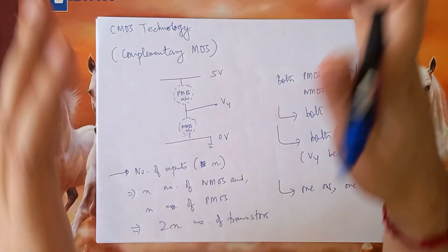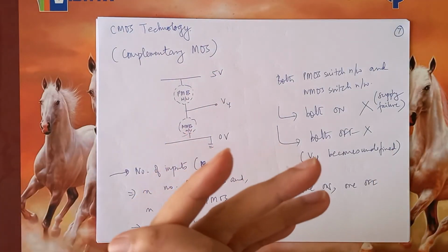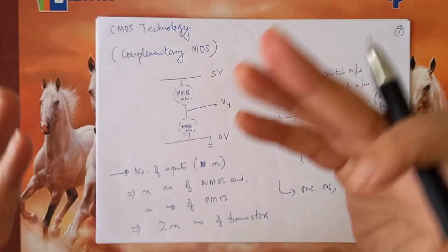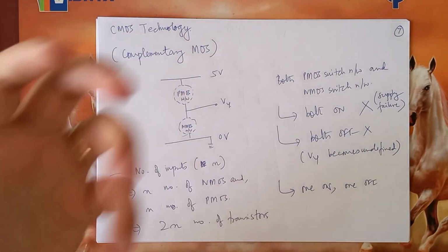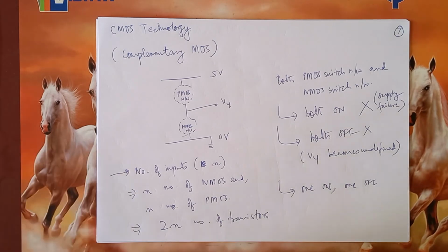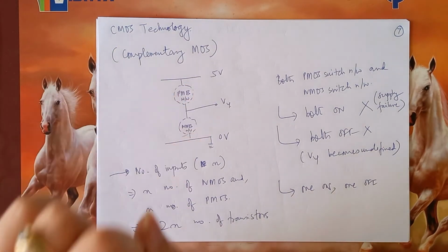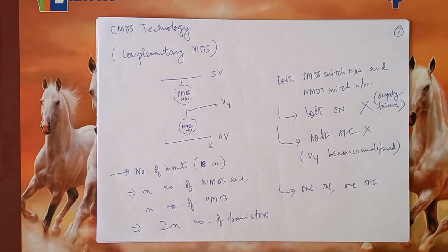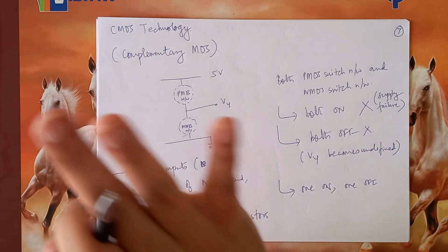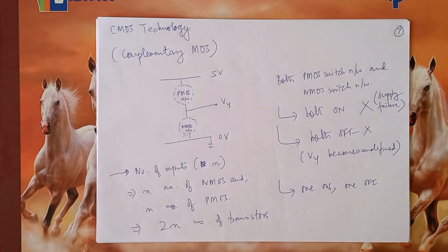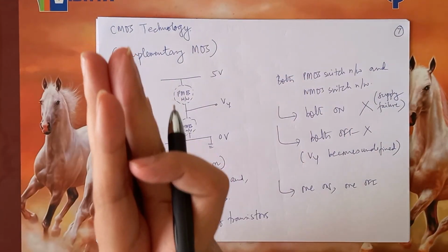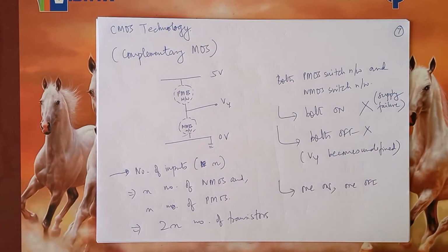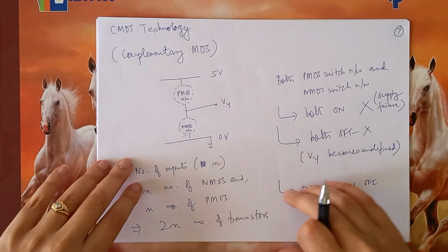That is, it can still operate, its linear regime and saturation regime will still be there. When you make the MOSFET smaller and smaller, its threshold voltage will reduce, its power consumption will reduce, but at the same time, it will not deviate from its properties. Well, there will come a time when it will deviate, but the degree to which you can make it small is extremely large. Let us see an example.